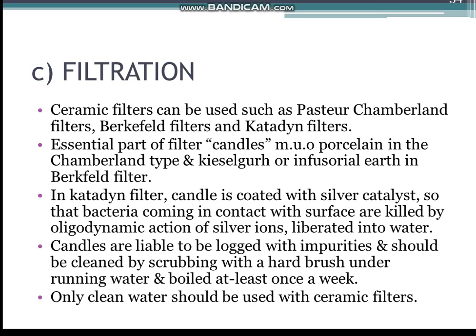Filter candles of the fine type usually remove bacteria found in drinking water. Filter candles are liable to be blocked with impurities and bacteria. They should be cleaned by scrubbing with a hard brush under running water and boiled at least once a week. Only clean water should be used with ceramic filters. Although ceramic filters are effective in purifying water, they are not quite suitable for widespread use under Indian conditions.